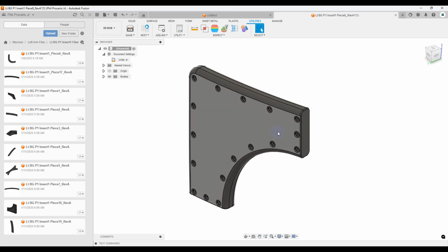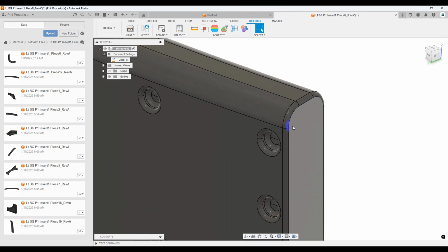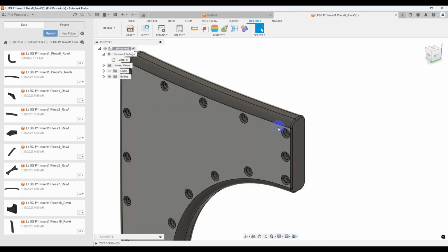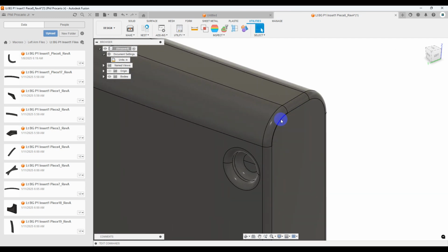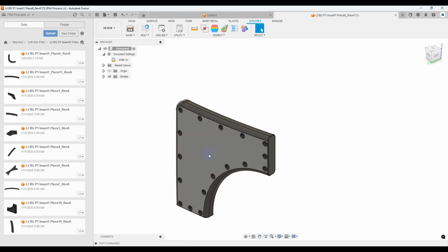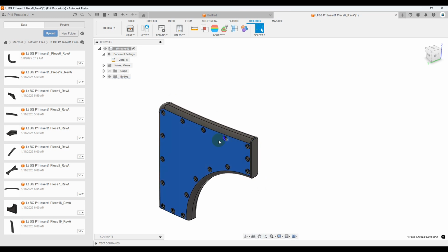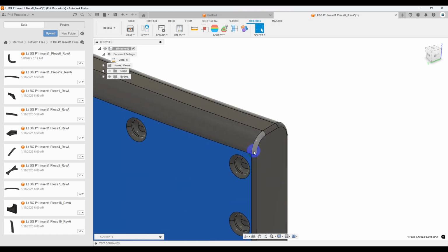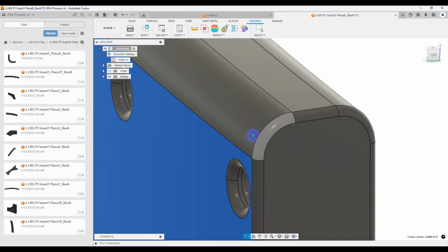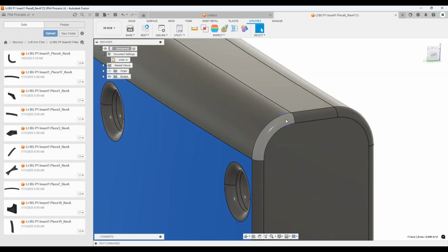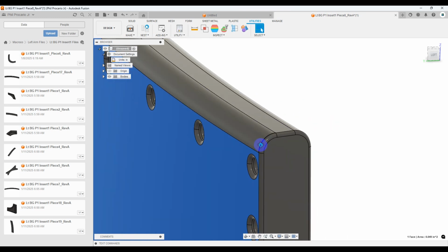So the first step that I found is looking at our CAD model. We need to know what we're going to be doing with each one of the pieces. One thing that's really nice about CAD is typically all of your faces in CAD are basically four-sided. And even the ones that aren't four-sided like this one, technically it is a four-sided NURBS. It's just been trimmed at this corner and this corner. So we have to keep that in mind. But it makes it really easy when we're doing retopologization because we already know that this is just going to be a quad that's split up. This is going to be a quad. It just continues on. And I'll show that in a later video.